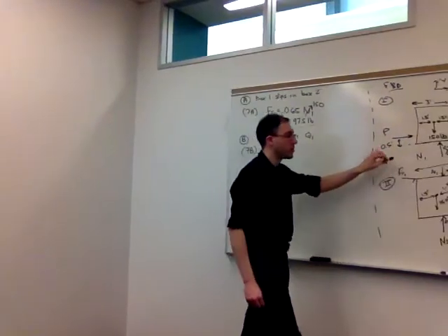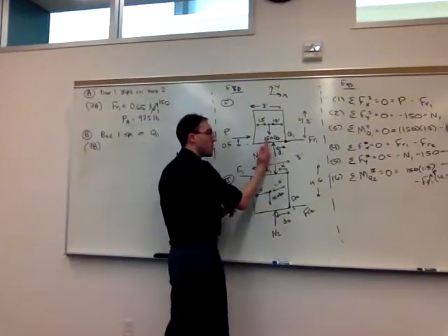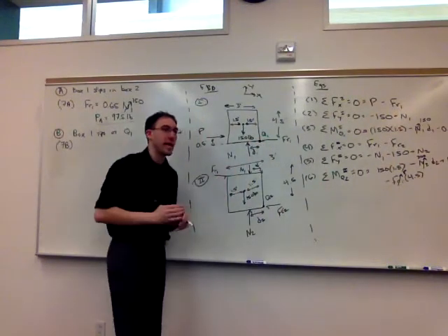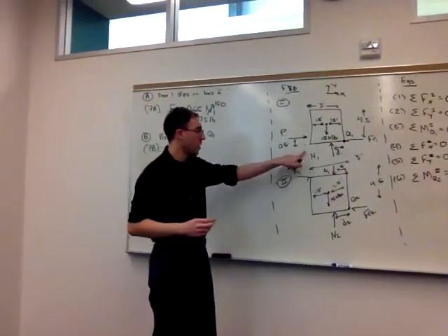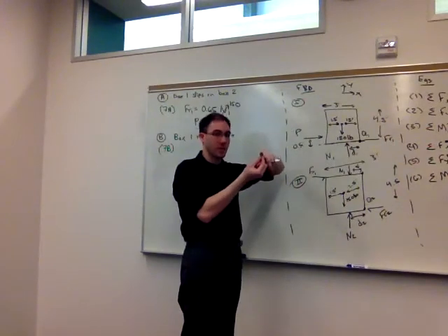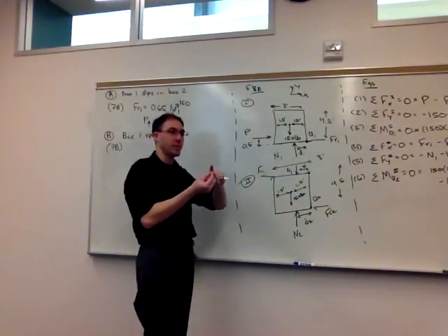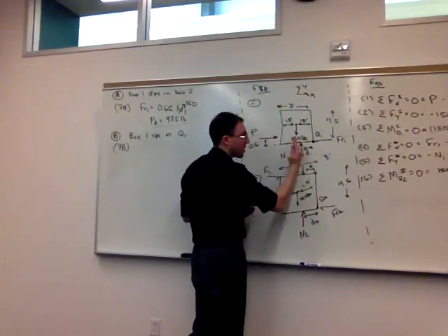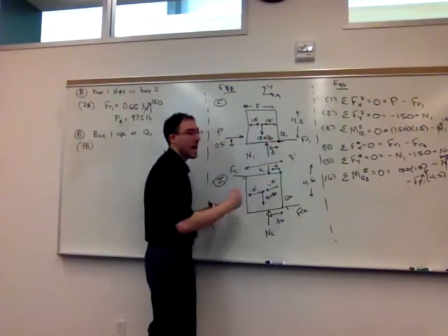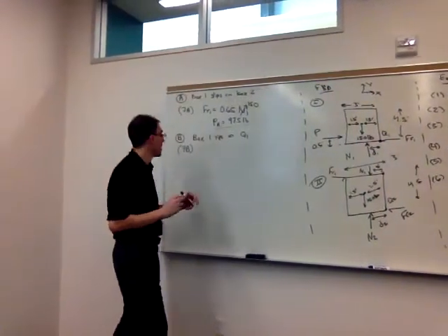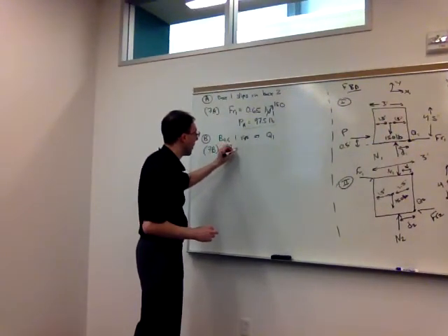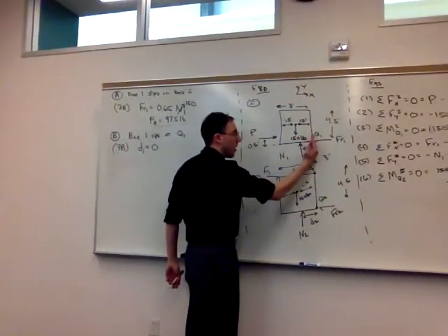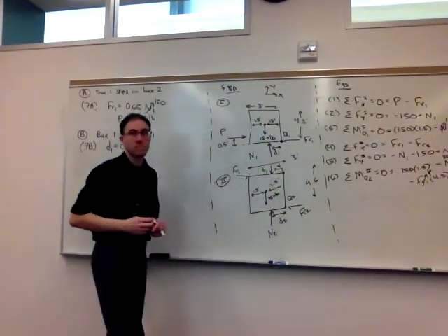D1 would equal 0. So when 2 surfaces are in contact, when the normal force is all the way under the pivot point, that's where we say that it's about to tip over. So it's a little bit different than if it was a point in contact with the surface. Then we say tipping is when the normal force is 0. So when the centroid of that distributed load is all the way at that extreme, that's indicating it's about to tip over. So the new equation is D1 is 0.